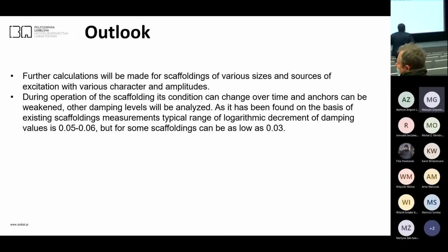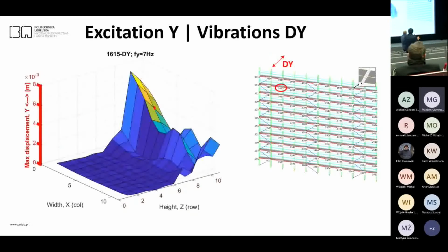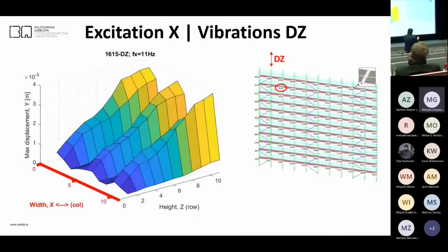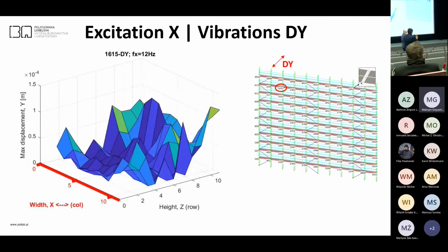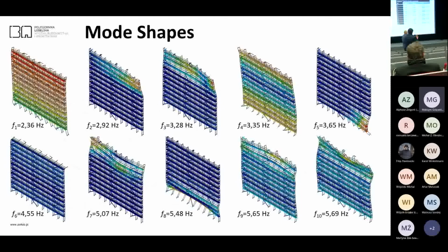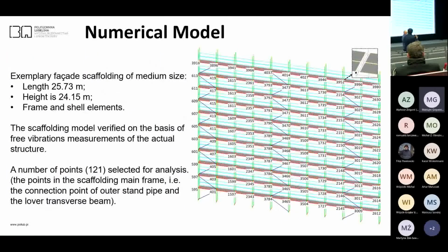I have two questions. First of all, how have you modeled it, because vertical and horizontal bars are not connected in the same plane? Have you taken that fact into account in your model? Yes, but it will change the solution. The second is that connections in scaffoldings are not exact. They are not welded or connected with pre-stressed bolts, but only made by humans.